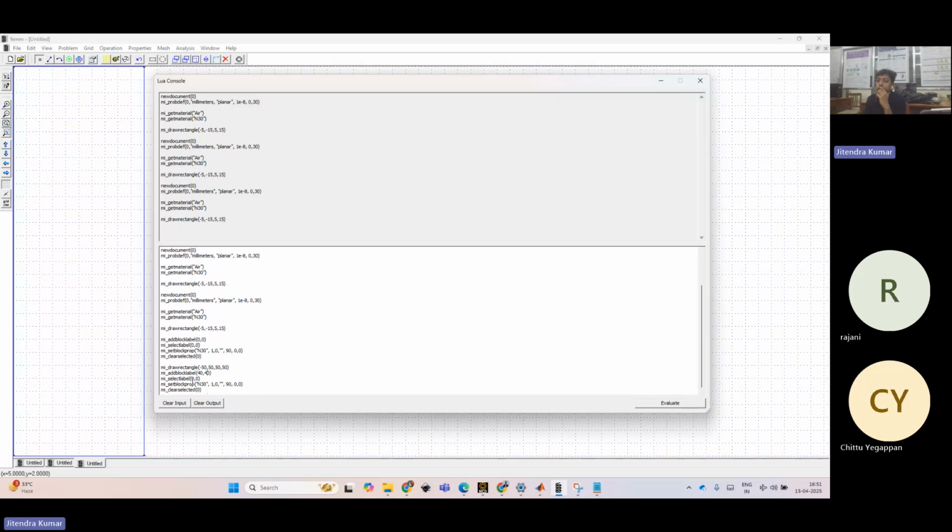Now we have to select the same label, right? So again, we have to copy this 40, 40 to select the label. Now, what should be the material now? The material should not be the one at 30, it should be air, as we have already defined, right? Now, the remaining you could keep, but air does not have any direction, so you do not need to give magnetization to the air, right? So we have assigned all the materials, right?